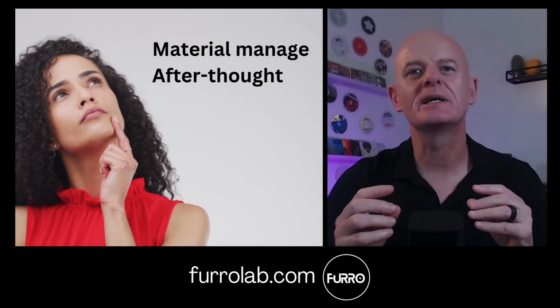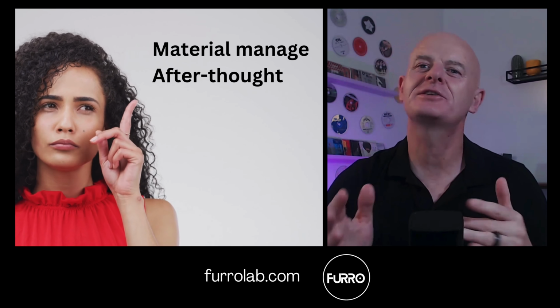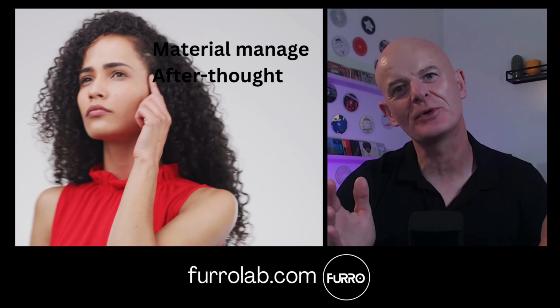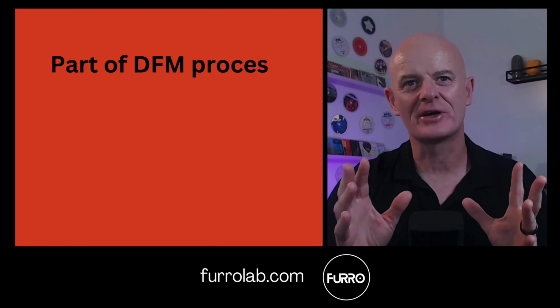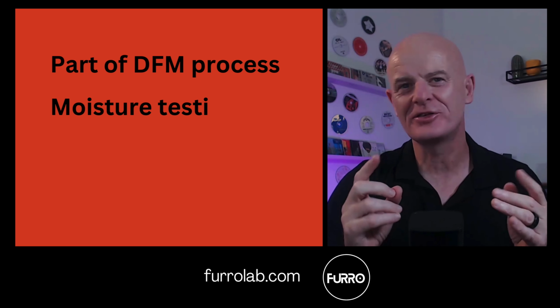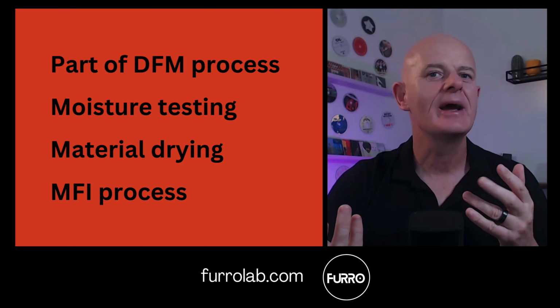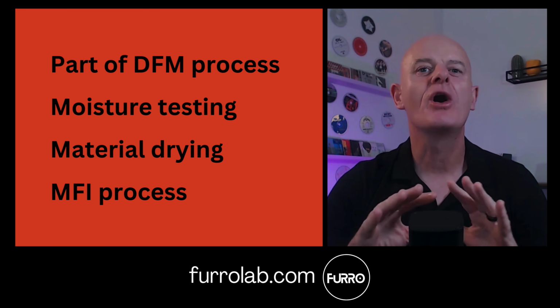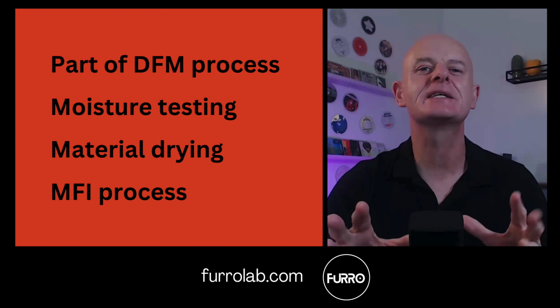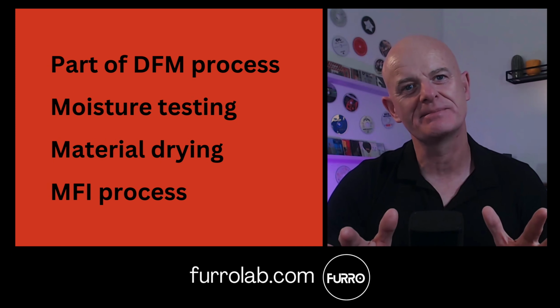Material management is often an afterthought, or maybe it's part of the root cause analysis when something breaks and crashes. Plan this up front. Make it part of your DFM process. Things like moisture testing, material drying, MFI process. All this needs to be in place and it needs to be a part of the daily process.